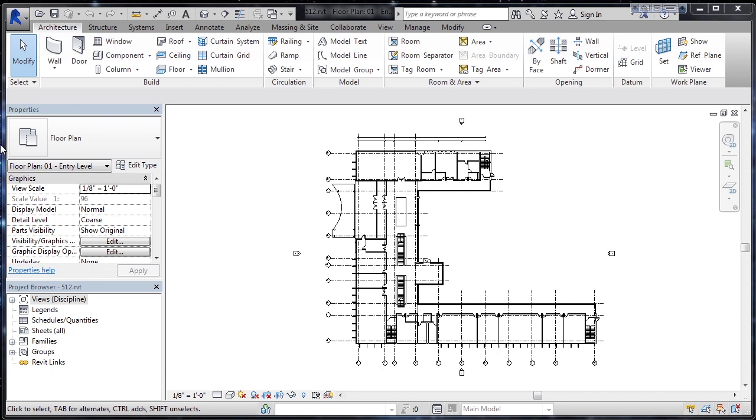In a previous lesson, we looked at creating work sets in a central file to actually share multiple Revit projects to one central Revit project. This example here is very similar, except what we're doing is we're collaborating with various different 2D CAD drawings into our Revit master project. So, for example, say some of us are working on a Revit model, but then some of us are actually working on 2D CAD drawings. First floor plan, second floor plan, maybe south elevations, north elevations, east elevations, maybe a roof plan. But all of those are 2D.